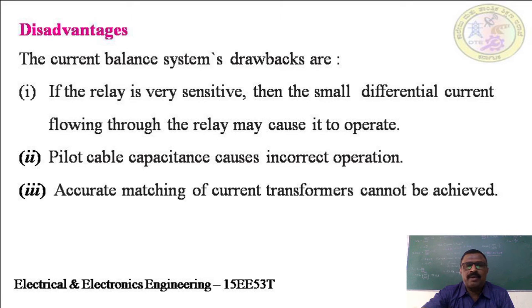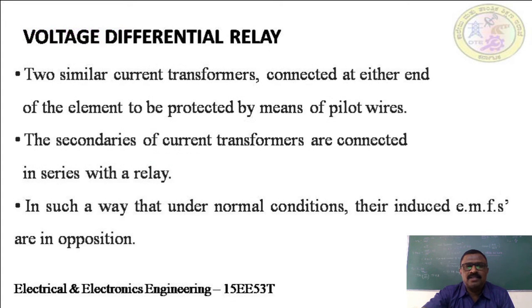So these are all the few drawbacks. It is very less sensitive. The pilot cables possess some value of capacitance, and accurate matching is not possible. So these are a few drawbacks or disadvantages of the current differential relay.